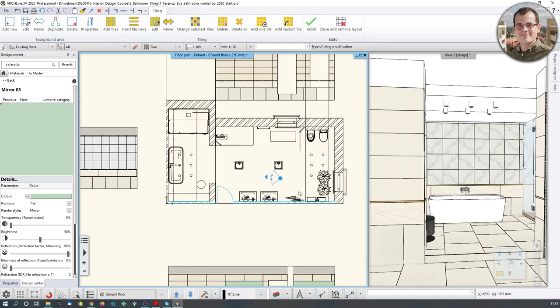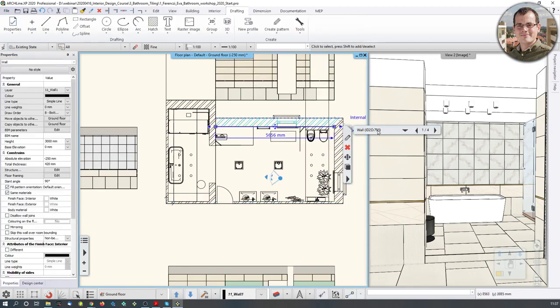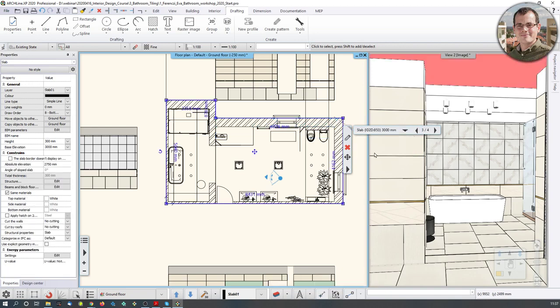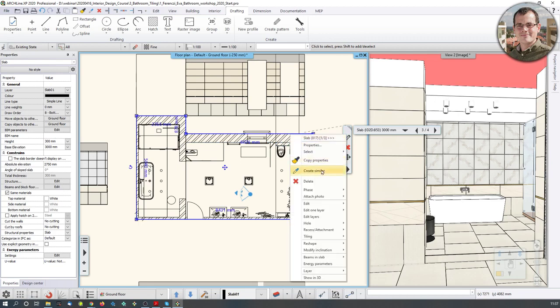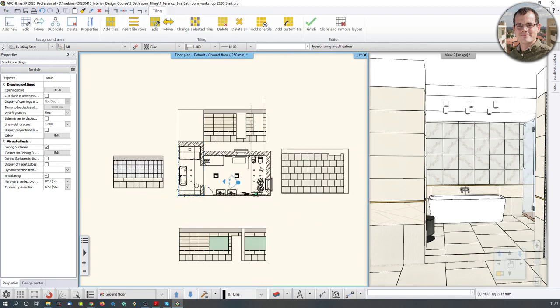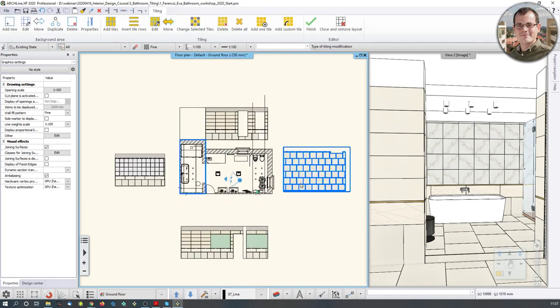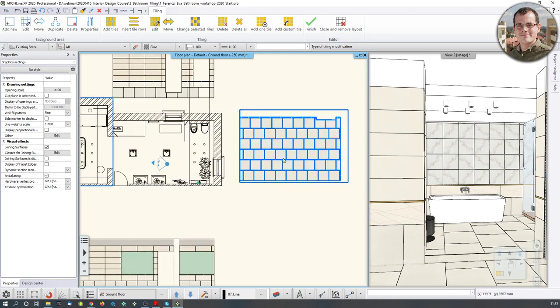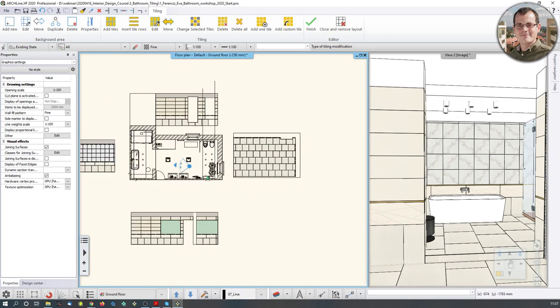If you want to create another one, or you get another one with the slab, you just click on the slab. Now I can't click on the slab right now because I have a wall above it, but you already know that with this jump list you can quickly find the slab. There are actually 2 slab pieces, I think I need this one. So if I right click and I go with tiling and the tiling on floor tool, then you know these things are automatically created. You can push this back to the original drawing, but that's the way to get a visual representation of how your tiles look like. So now again, I could be going in and creating multiple multi-layered styles over here, but that's the general idea.